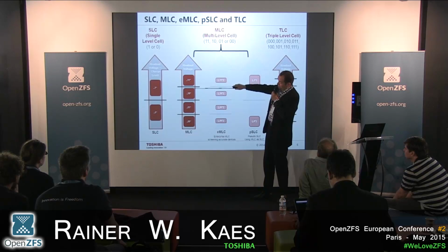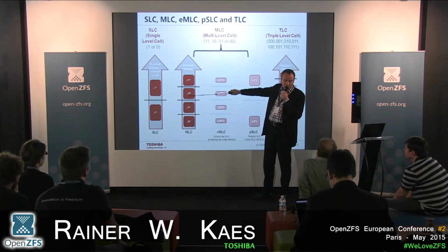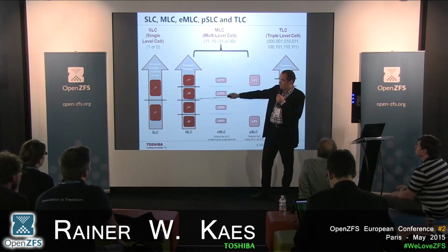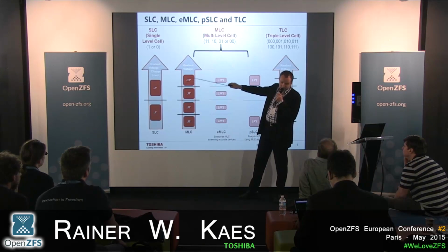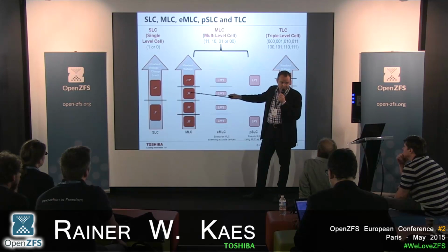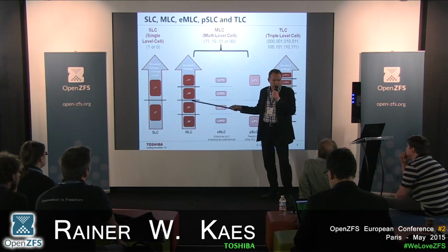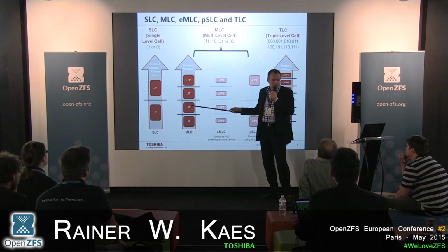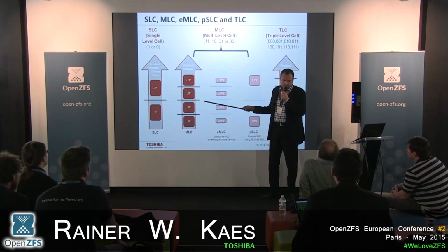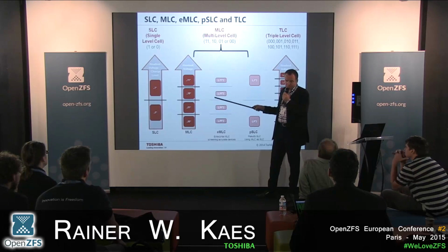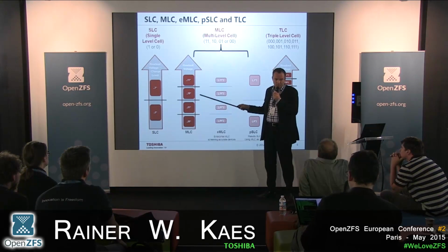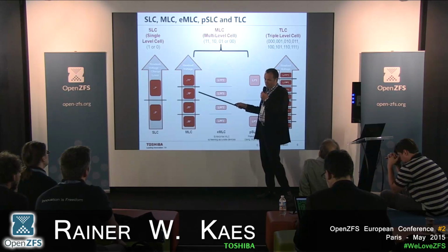And if we have written, let's say, 66% of charge, and then the leak-out process starts because of the damage, we reach the wrong value much quicker than for the single-level cell. And this is why multi-level cell, even though it is on the same physical structure, is less robust and can tolerate less erase flash damage than the single-level cell. If just a few cells gave out the wrong value because of this leakage, we can still tolerate this because there's an error correction. But if the writing process into a storage device is well distributed, many of them will fail if many have the same amount of damage. Then the error correction would not really work anymore.